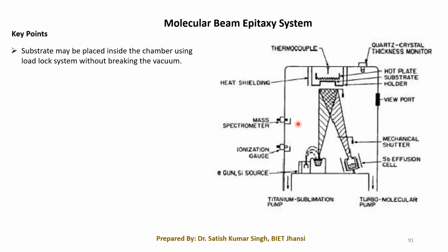But in the MBE case, if we have a cleaning mechanism within the system, and we place our wafer inside and clean it there, it is called the in situ cleaning process. If there is no mechanism within the system, and the wafer has to be placed outside the system to be cleaned, it is called the ex situ process.